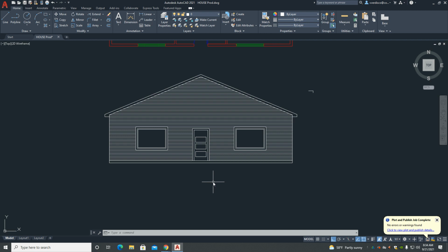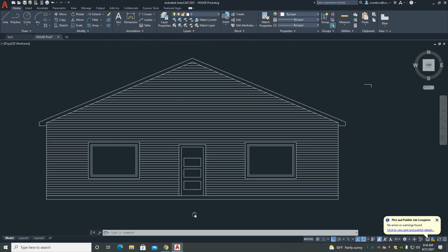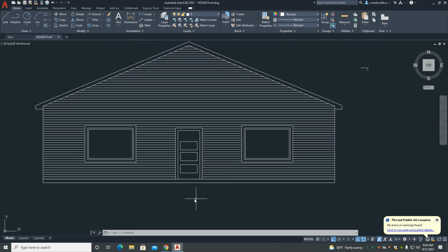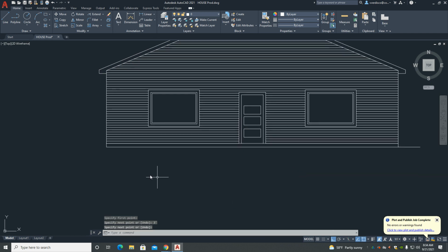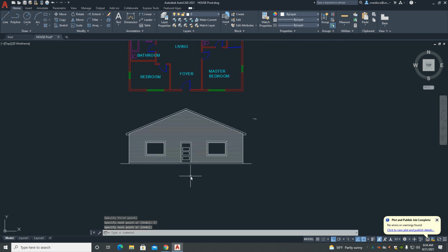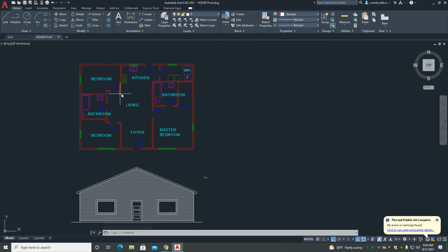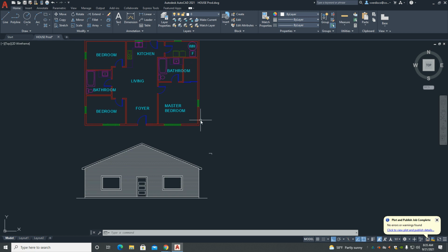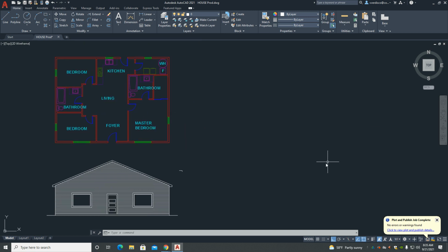Maybe throw a doorknob on there. Do a better job with the panels than I did. And if you want to, you could also put on a grade. So we could do a 3 foot here, 3 foot on this side. That's it. So there's the front elevation, and everything else carries through. You build all the others. You can either rotate this and build them all lined up this way, or you can build each side facing sideways and upside down. I like to rotate this, copy it and rotate it to build each side.